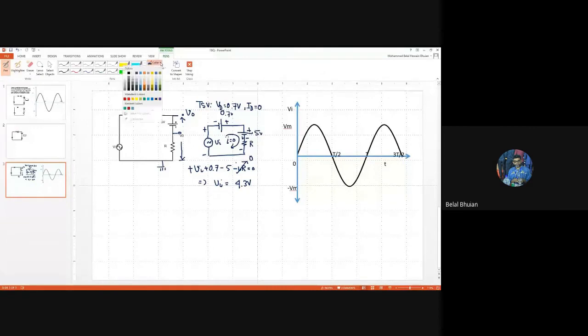So the next step would be to draw our transition state line. Is 4.3 above or below? Above. Since it has come positive, it should be above. If it had come negative, it should be below. Now we just put it qualitatively, without any scale, roughly somewhere here. This is our transition state line, that means our Vi equal to 4.3 volt line.